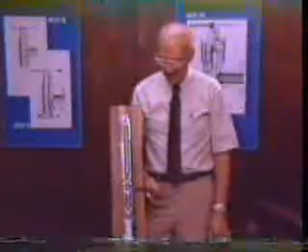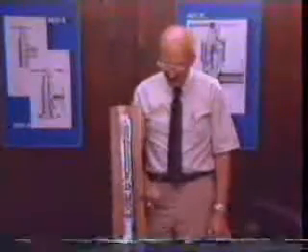Shown here is a 1.5-inch OD pilot-operated gas lift valve. This is an ideal intermittent gas lift valve because with the pilot, we're able to get complete spread control, very small spread requiring very small ports, but simultaneously with the motor valve section, we're able to always maintain a large port for passing large amounts of gas efficiently.